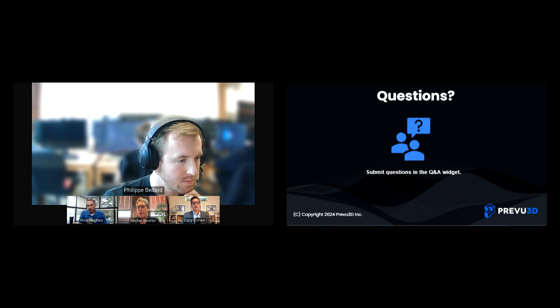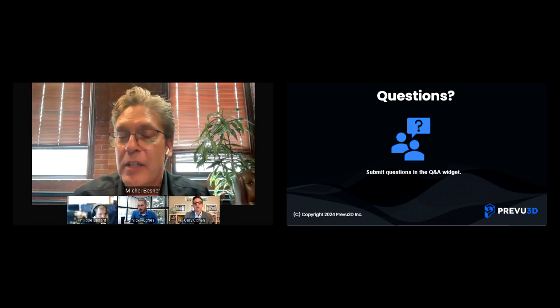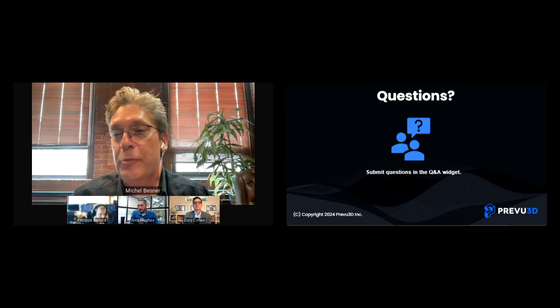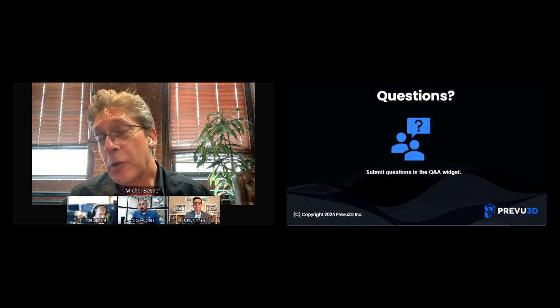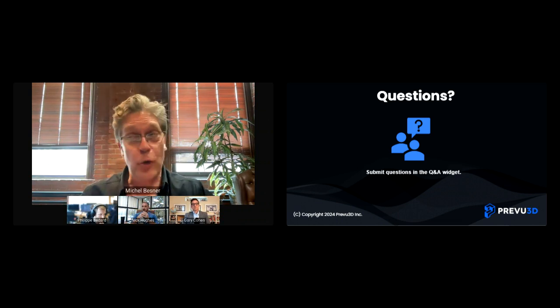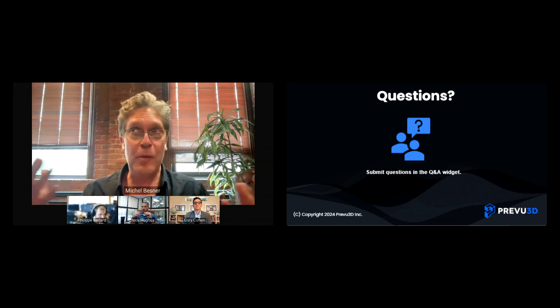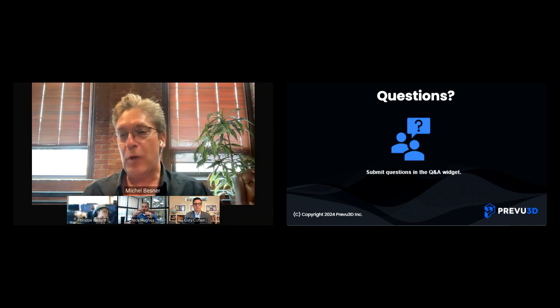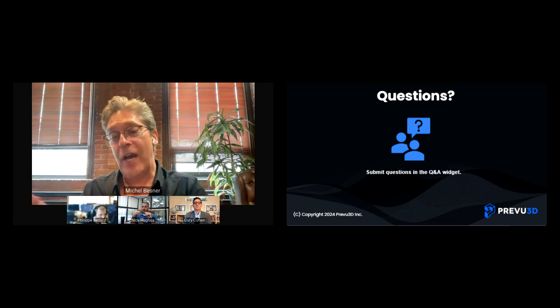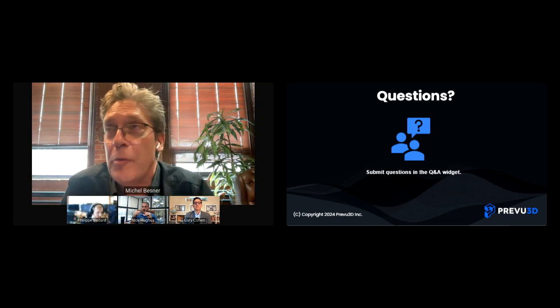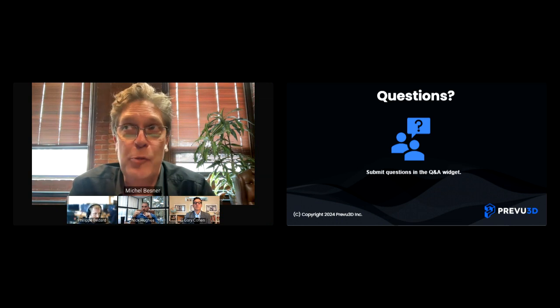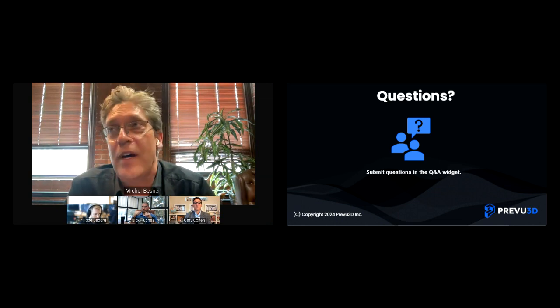Yeah. So we're getting a lot of questions, which is great. Dietrich, for example, is asking about the compare tool that we have and how much we use it if you've done your scan to BIM or scan to CAD conversion. Actually, it's an integral part of doing a scan to CAD, unless, of course, you have no CAD at all and you just want to start from scratch, then it's not as useful. But often you do have a CAD model somewhere that you've done in the past, and the question is how to validate whether that CAD version is close enough. If you have a CAD version that you did last year, you can start from that instead of starting from scratch on the entire scan to BIM work, and you're going to save a lot of time. If you can identify the few areas that have changed since the last time you did your CAD model, that will cut down a lot of hours, a lot of time.